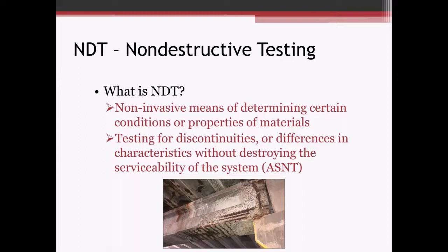So if you think about without destroying or compromising the serviceability, taking a core out of a structure could be considered non-destructive testing, but I think most people consider taking a core out of a wall or a slab destructive. And certainly when we test that core, we're destroying it.